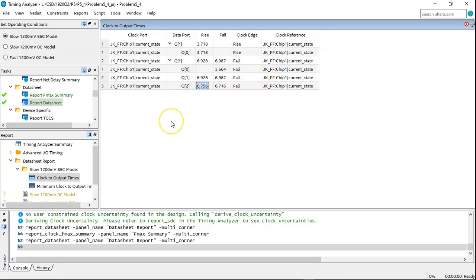You have to go adding delays from one flip-flop to the next, because the next clock which is triggering the next flip-flop, for example the chip 2 and the chip 3, the two flip-flops that go after the chip 1, are triggered once the Q is settled after the propagation delay of the chip 1. So you see, this is really a complication.